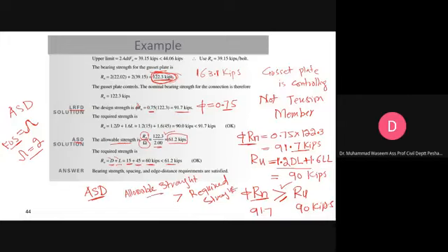So allowable strength is 62.1 and this one is 60. Okay, so this is okay. Okay, the bearing strength of this connection, spacing requirement, edge distance requirement are satisfied according to AISC recommendation.